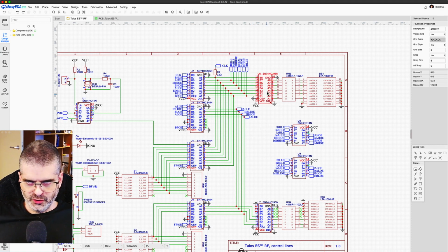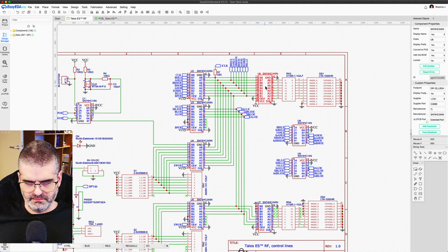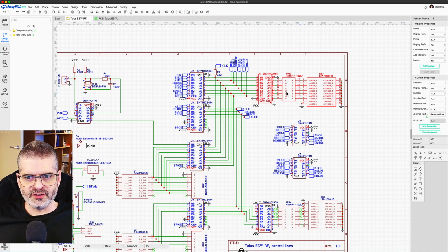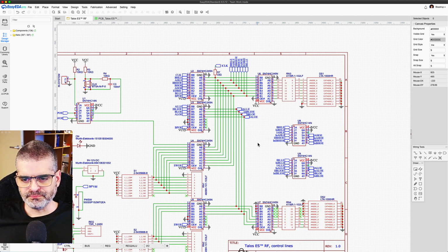Now the first thing you do is pass these local lines through another buffer and a 1 kilo ohm resistor network, and you send them to an LED bar so you can see what the control signals are. The same thing for the rest down here. I'm having to use two buffers because there are a lot of control signals this time, more than 8. So I think there are 12. Yeah, 12. So I need two buffers for each selection and two LED bars to show everything.